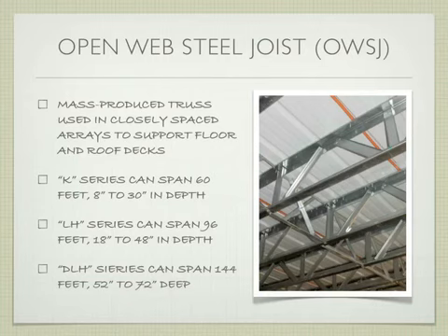We will cover trusses more in depth next class, but we're going to certainly start on trusses today. The first type of truss that we'll talk about is what's called an open web steel joist. Okay, so by joist we're meaning that it's on the smaller scale of trusses. It is a mass-produced truss, and the idea of a truss is basically that we're going to use small pieces that are spaced relatively closely together to support the same amount that a large beam would have to support. Right? So we're using smaller pieces, and we're taking away more of the non-working structural elements to make these.